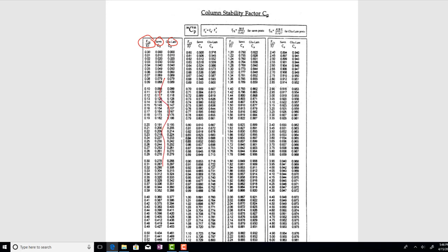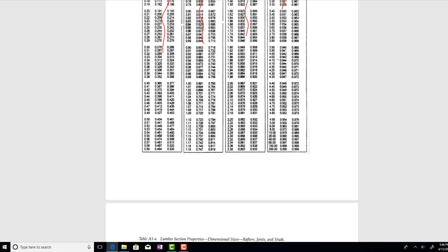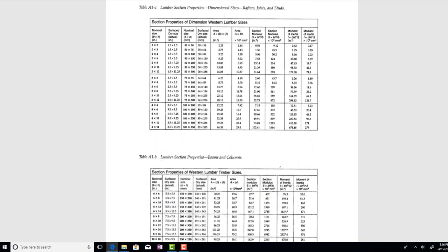And of course, it's really one giant column split into 4 different sections. It's pretty easy to jump in there and grab your column stability factor off the table. Out of your appendices, if you need some shape properties, meaning the geometric properties for either dimension lumber or beams